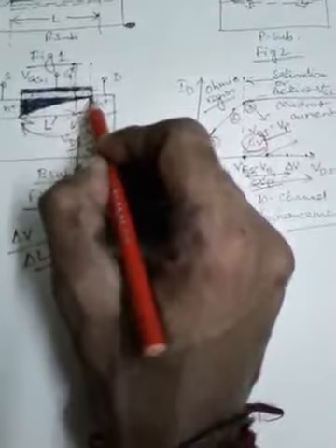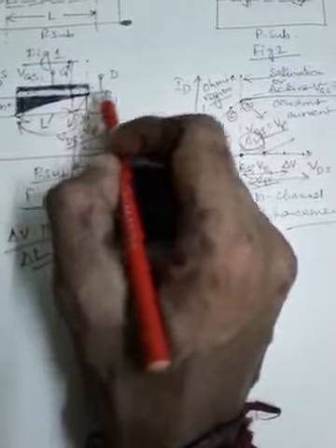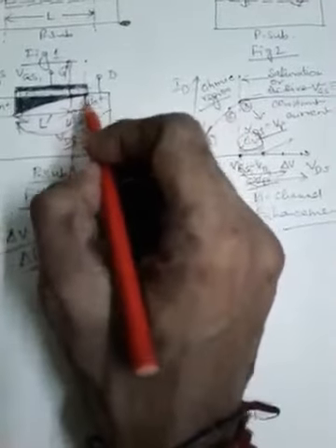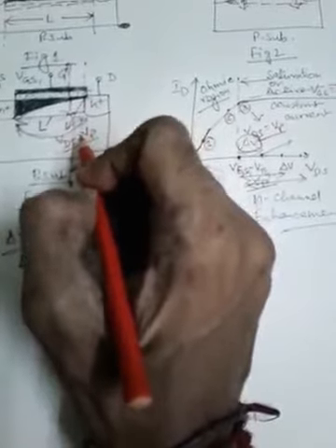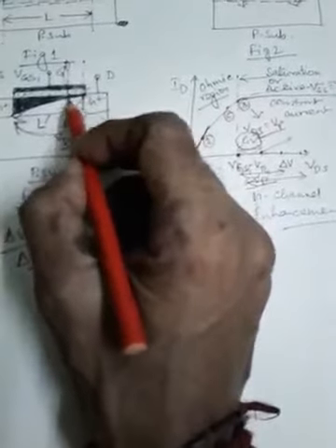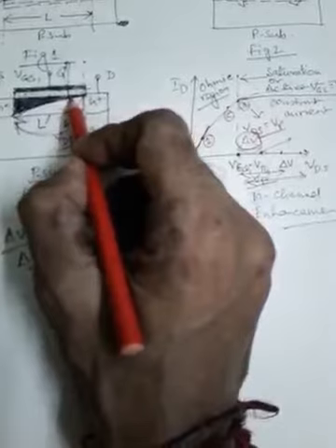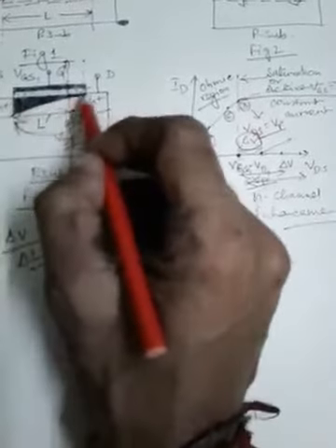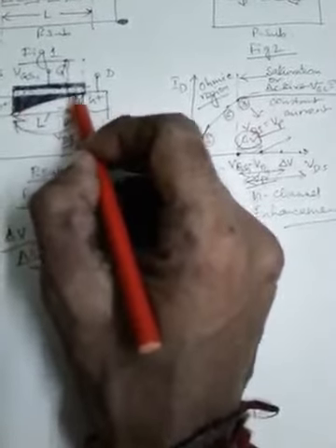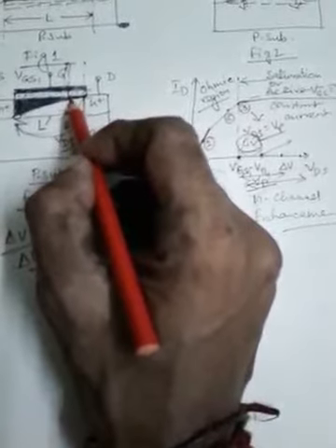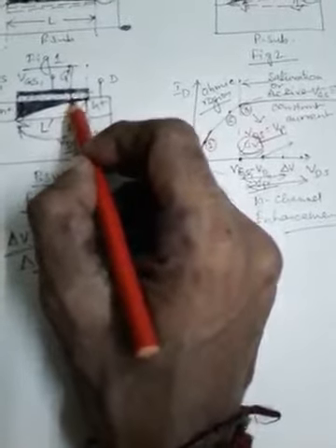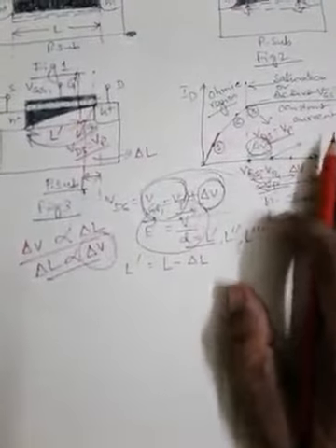So this point of pinching off of the channel in this MOSFET will be moving towards the source terminal, and the pinching off of the channel is happening earlier than the previous case, as more and more voltage is applied between the drain and source terminals.